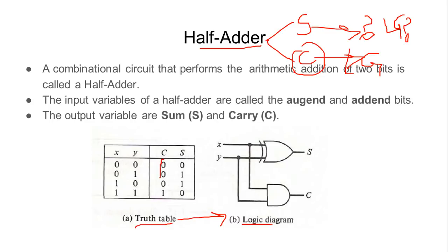So if I look at this particular output of the carry in case of half adder, I can easily see that this is purely resembling the AND gate. If you remember the AND gate truth table, the AND gate is working the same way. If I would say which logic has been used here, then it is very easy to understand that it is the outcome of AND gate.